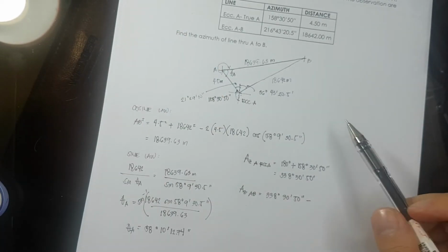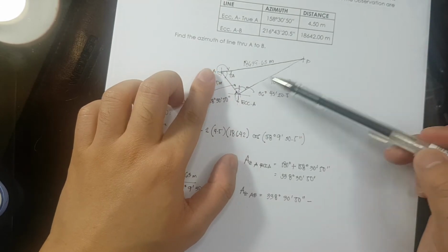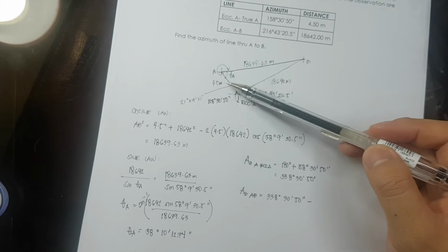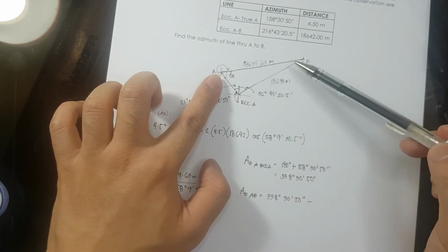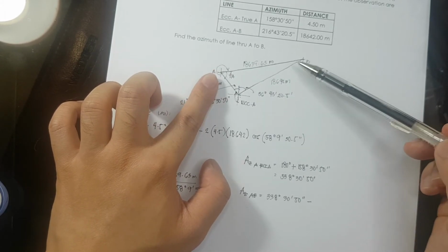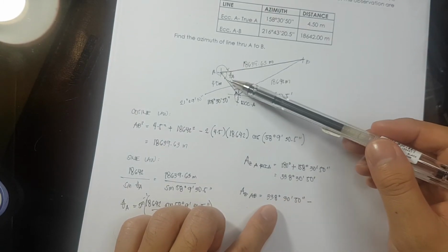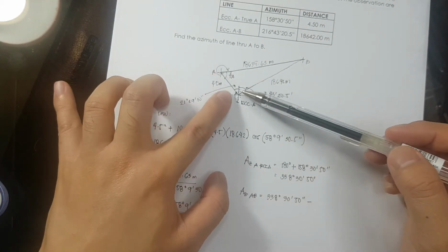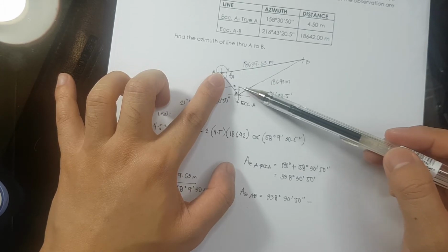So this time, ang gagawin natin para mas mabilis, we subtract the remaining interior angle aside from the angle that it is involved, no? Dito ang involved is theta A. So isusubtract natin yung theta A sa interior angle ng triangle na to, which is 180. Then yung remaining is yun yung isusubtract natin sa azimuth reference natin, which is this, okay? So azimuth A to eccentric A minus the interior angle of theta B and this one.